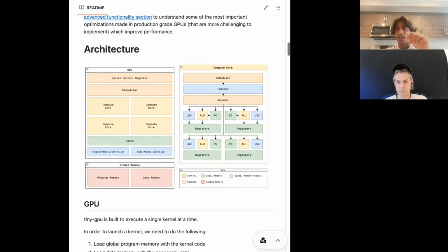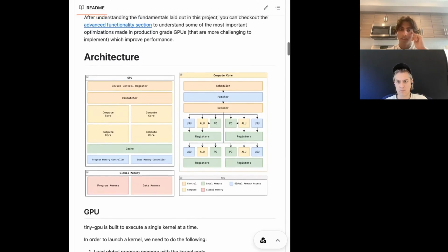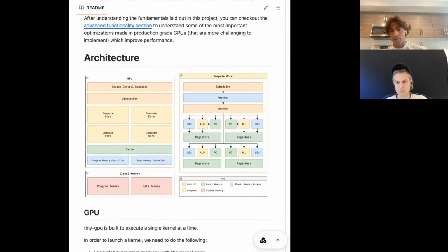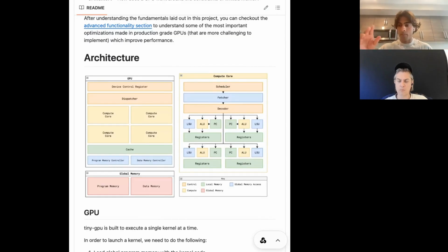So let's look at the actual compute resources that are in the thread. This is the last piece on this diagram, and then we'll go on to the next diagram. Within the thread, in my design, there's basically 4 key pieces of memory and resources. Each thread has its own register file that we've already talked about, and its own ability to perform computations on some data. And then, importantly, it has its own program counter, which means that each thread can be on its own line of the program.